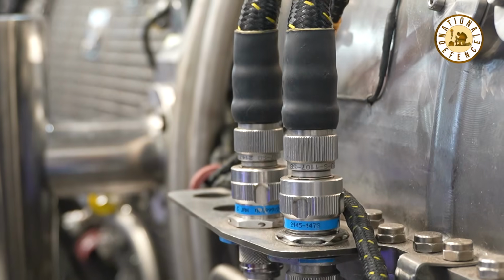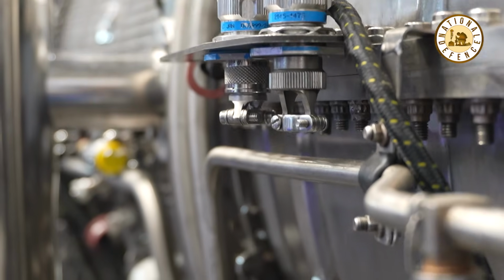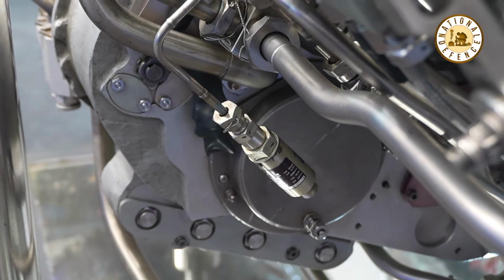So then, as I said, EBPVD, TBC, then the blade will involve broaching, factory cutting, and a lot of machining. Together, from the casting to the machining, it may take a minimum of 2 to 2.5 years. Then we have to test those things.